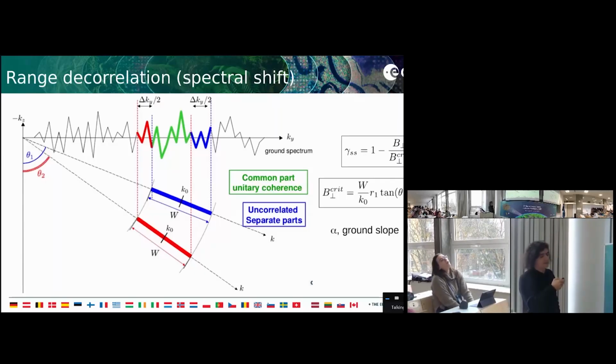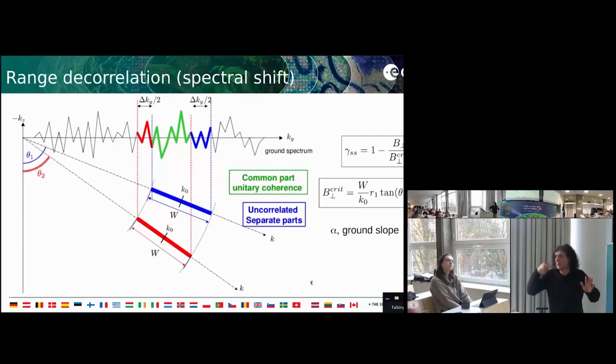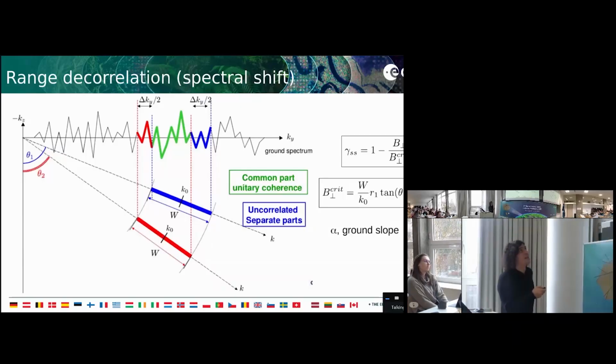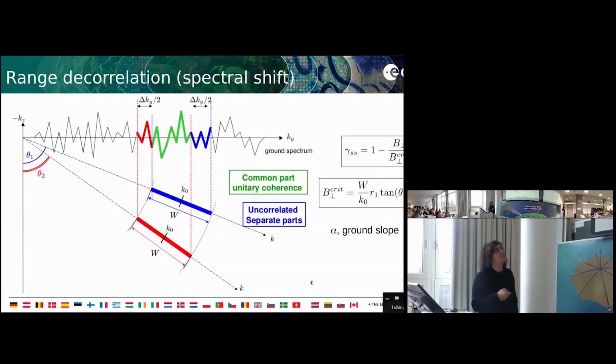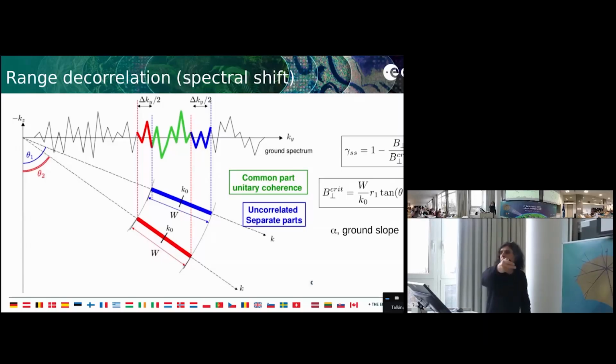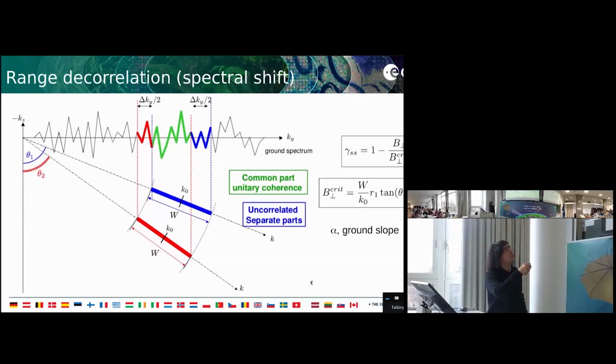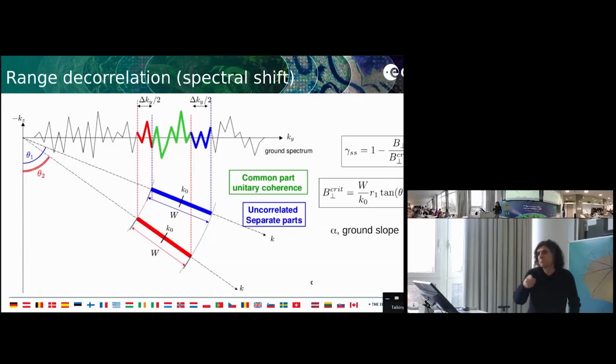This is a spectral domain, the vertical spectrum. So you take your environment and you apply a 2D Fourier transform in elevation and in ground coordinates. And the SAR acquisition in this domain is comparable to a selection. You are selecting the spectrum of the environment over a bandwidth which corresponds to the bandwidth covered by the pulse you transmit. The width here corresponds to the bandwidth of your signal, and the location corresponds to the incidence angle you are using when you perform the first and the second acquisition. This is called the Fourier slice theorem, something some people know.